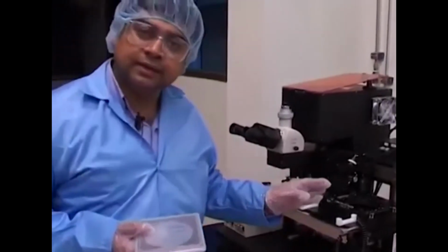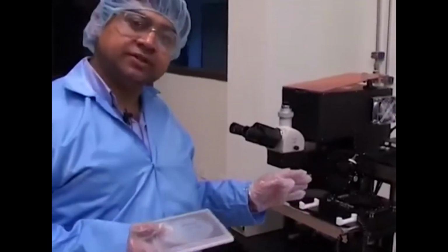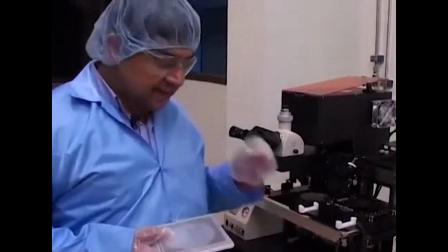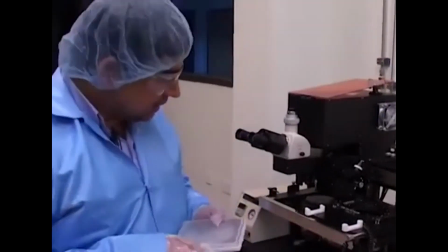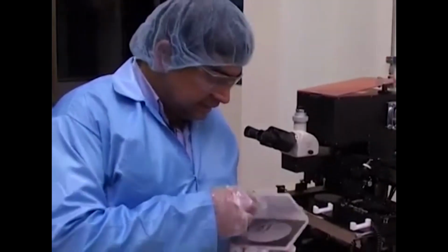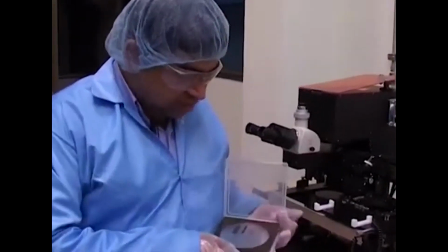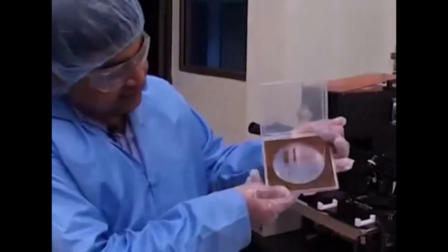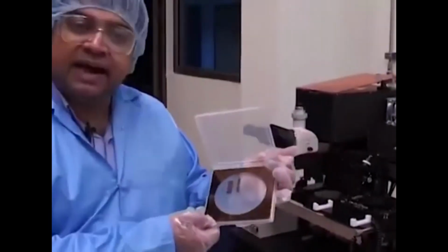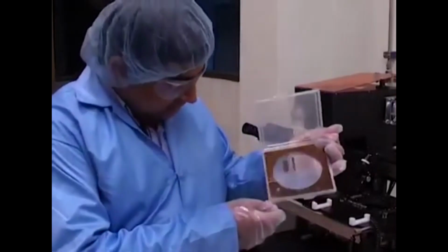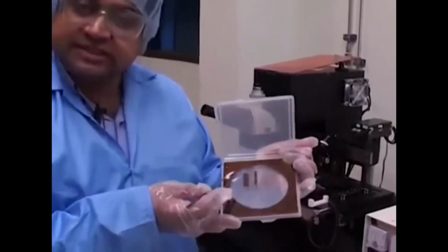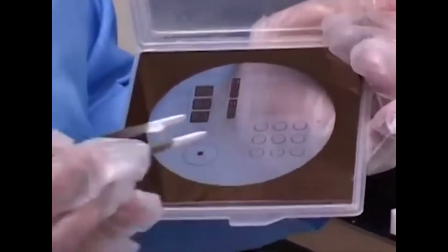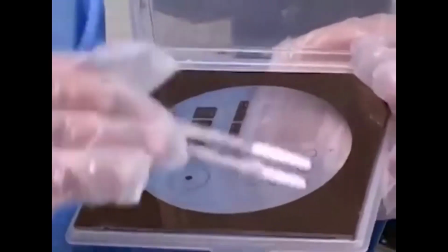So essentially this is called the photolithography equipment, and this is used for exposure of the resist to a very characteristic frequency of light, mostly in the UV area. Essentially here what you do is use something called a hard mask, which you can see right here. This is actually a glass chrome mask where, if you look closely, these features really are at the micron scale, and these have been made using laser etching in a film of chrome,